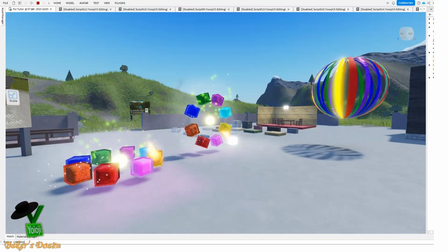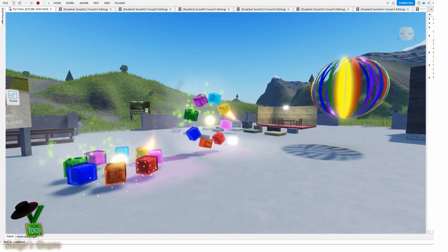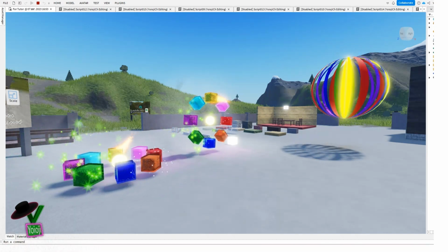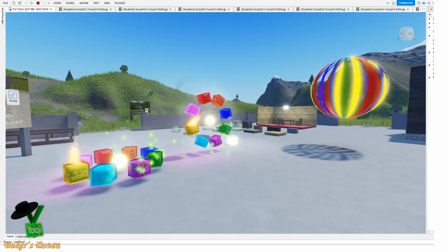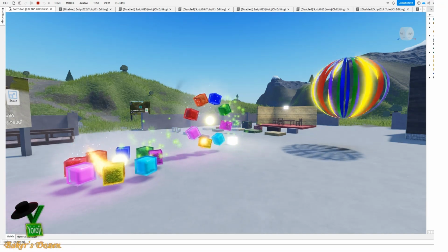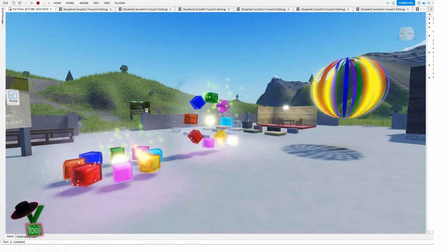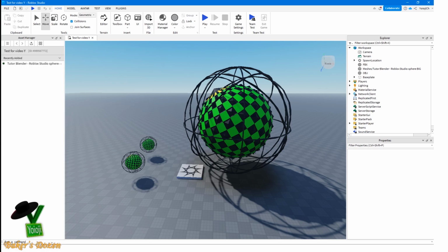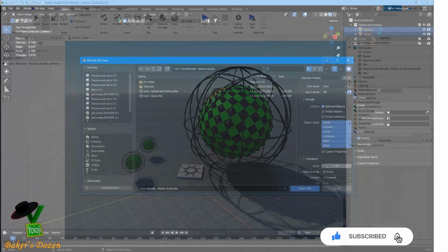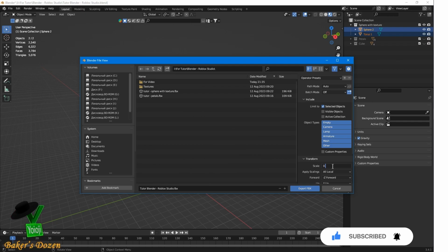The advantage is obvious. Now you know about these disadvantages and advantages of this or that way of importing 3D models into Roblox Studio. Let's move on to the problems that you may encounter during the import process. What should I do if, when importing the FBX file, the model becomes very large? We have already talked about this when exporting a model from Blender. In the scale parameter, change the parameter to a small value. I usually set it to 0.100.